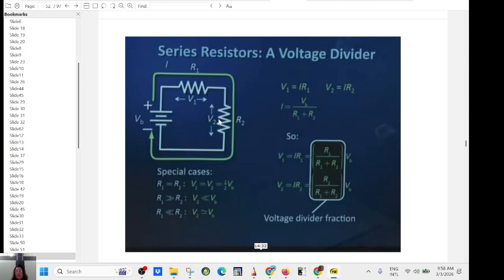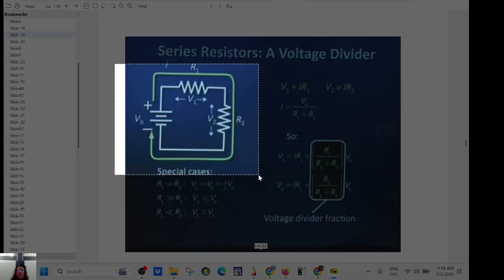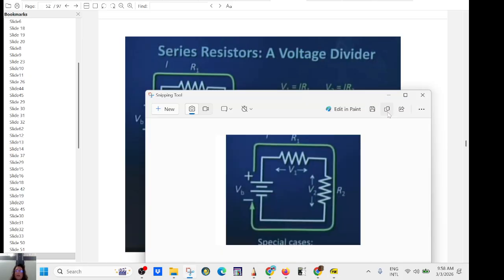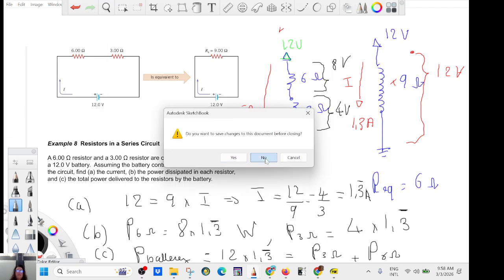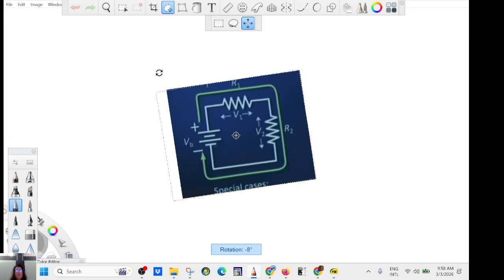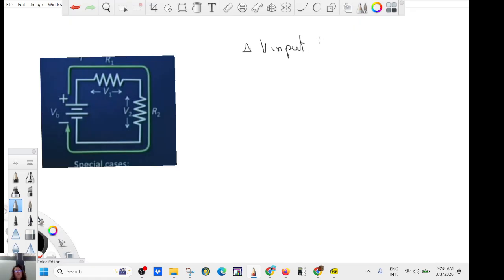So I will let you do the math. You're using Ohm's law, you have all the details, so you can do that on your own. But basically, I give you the trick, like a shortcut. It's called a voltage divider. You need to have 2 resistances. So in that case, it goes like this. You have here your input, that will be your input. So for example, 5 volt.